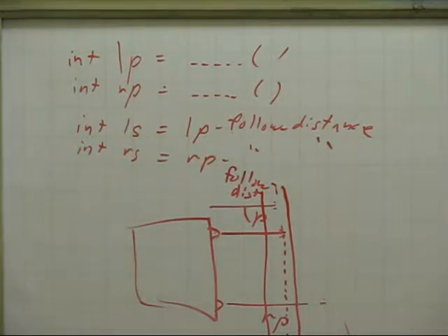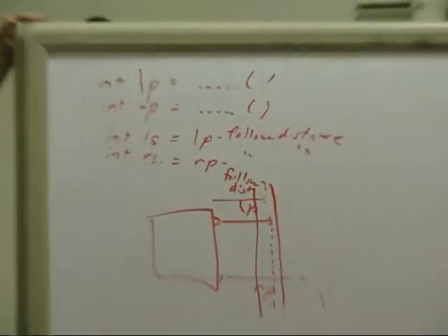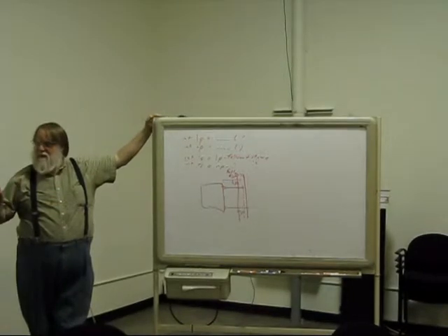If you use this robot, take phase 3 and reverse that threshold comparison, it becomes an object avoider for the floor. Basically, whenever it sees something close to it, it'll back away from it. Whereas right now, it's whenever it sees a big distance that it backs away from a big distance. So you might want to try and tweak up your phase 3 to do that.